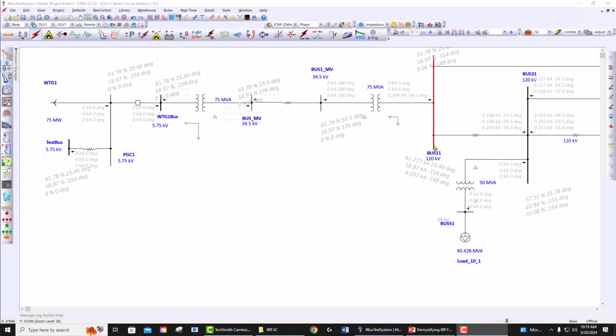Now, if the X/R ratio of the transformers, lines, cables, whatever is in front of the IBR does not match the angle difference between the voltage and current injections of the WTG or IBR, then we're going to have a problem. Basically the network dictates that there should be a certain angle difference based on the X/R ratio of this impedance, while the IBR wants to inject its current based on a different angle difference. So this can create some sort of an angle rotation or instability.